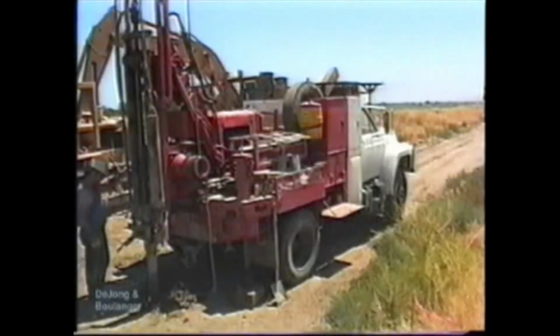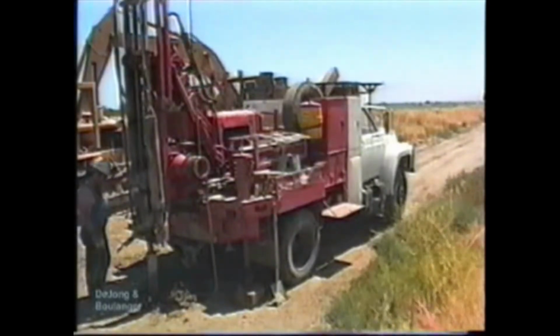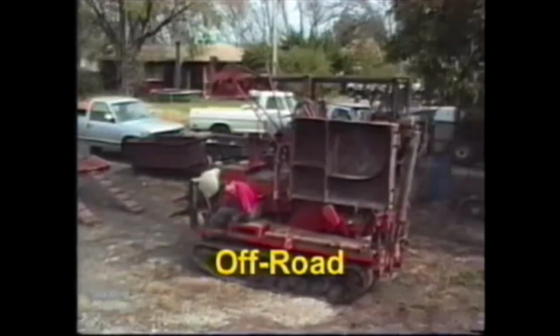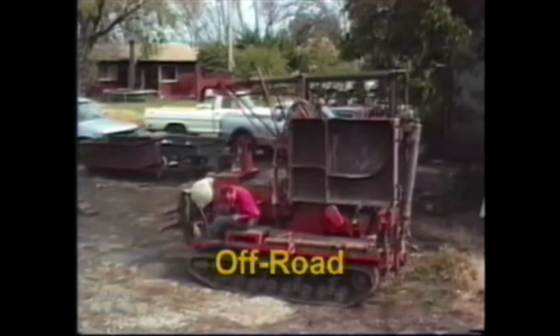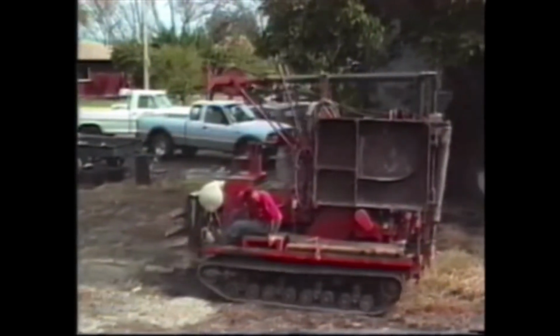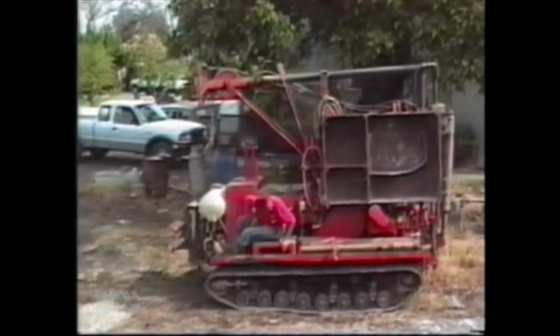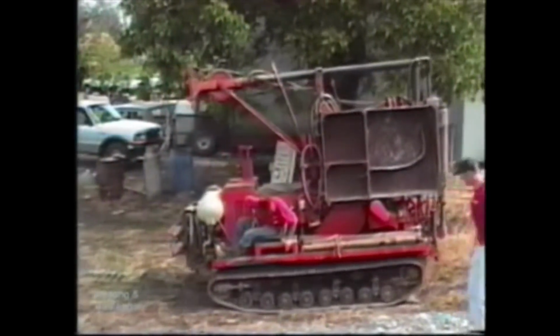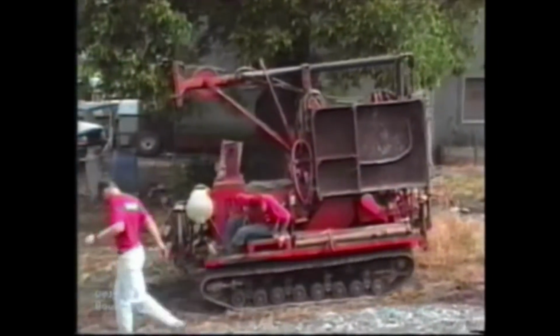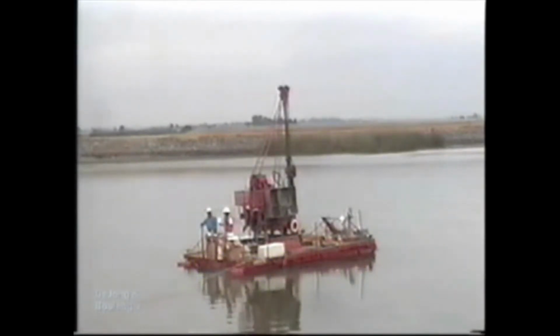A highway rig is used for sites that are relatively level and easy to access. Off-road drill rigs are used when access to a site is unusually difficult. Typically, these drill rigs are either mounted on large rubber-wheeled trucks or on tracks. If an off-road drill rig cannot directly access a site, a helicopter may be used to move it into position. For soil investigations beneath bodies of water, an overwater drill rig must be used.